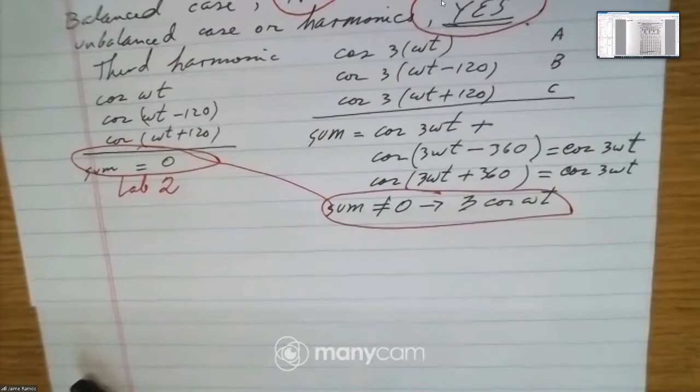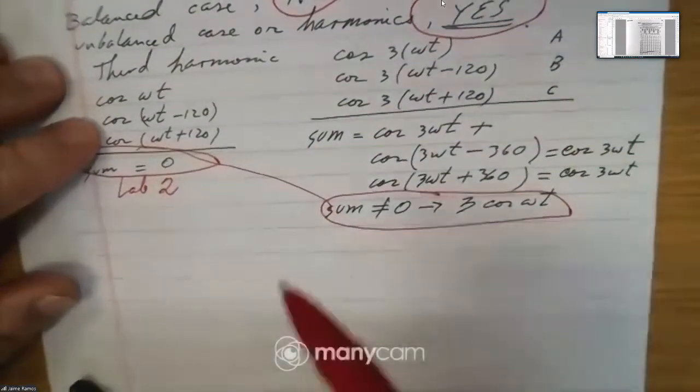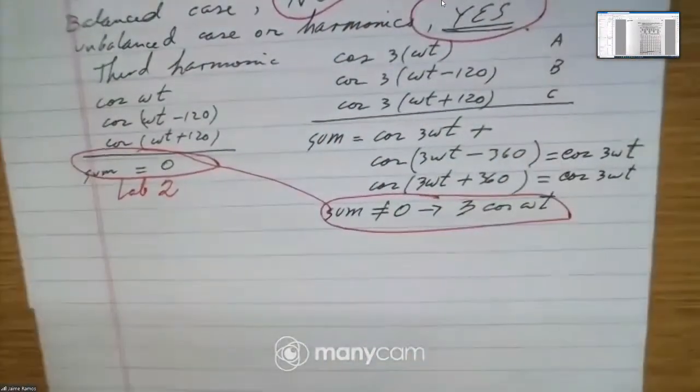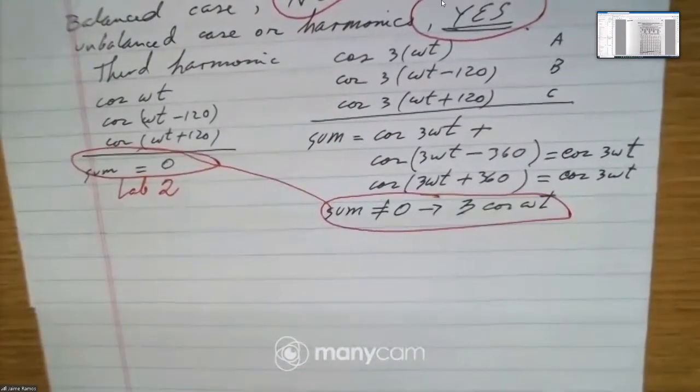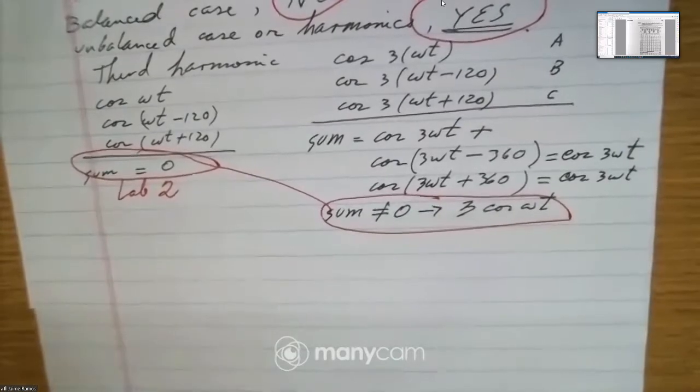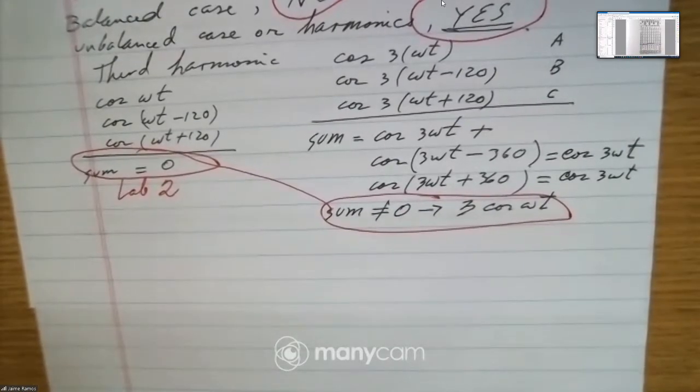Okay, so those 3 are called current carrying conductors, because there may be in the raceway other conductors which are not considered normally current carrying conductors, such as the grounding equipment conductor. Okay, so these tables for ampacity are good for 3 conductors. And then what happens if there are more than 3 conductors in the raceway?